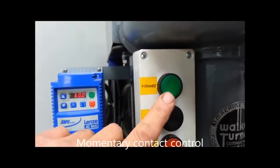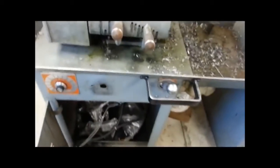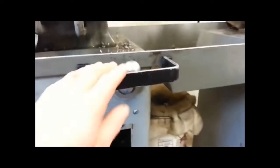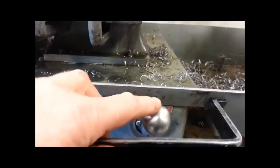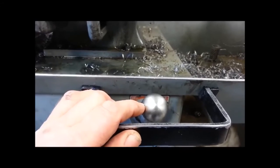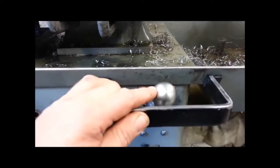These are momentary push buttons. And this one is on a maintained type control. I use the factory switch here, and it's just the old drum switch. It's a 3-pole drum switch, but I'm only using one of the poles to activate the VFD.